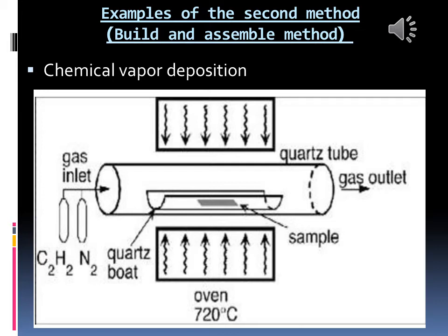At high temperature, the hydrocarbons are broken at the hydrogen-carbon bond, producing pure carbon molecules. Then, the carbon will diffuse toward the substrate, which is heated and coated with a catalyst, where it will bind. Carbon nanotubes will be formed if the proper parameters are maintained. The advantages of the chemical vapor deposition process are low power input, lower temperature range, and relatively high purity.